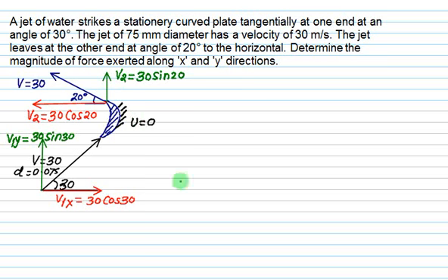what? 0. Mass flow rate is given by rho times a times velocity. Remember, area and velocity must be what? Perpendicular. So that is v component, not either v1x or v1y. Jet is going this way, so we want this area. So we are interested in v, and this section equals to what? Pi by 4 d square.